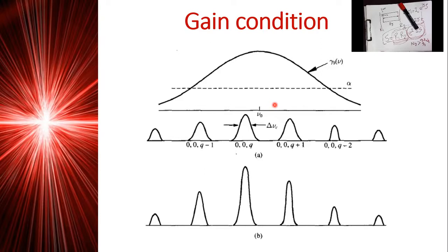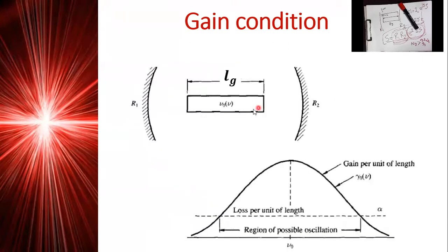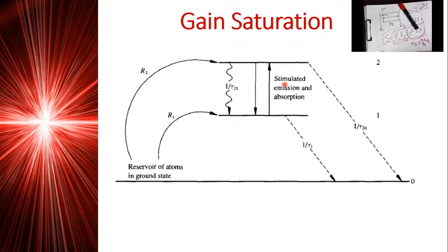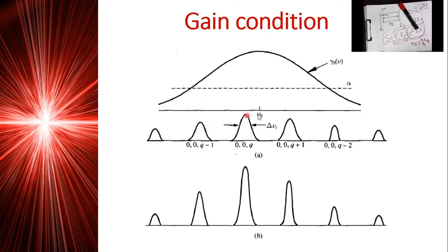Okay, now maybe you can ask yourself a very important question. Based on our understanding, this amplification is going to affect the signal per round trip. That's why this is the first round trip, the second round trip will have a higher peak, and so on. So per each round trip inside the optical cavity, your signal or your resonance will be amplified.